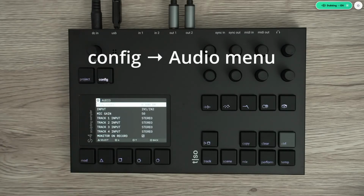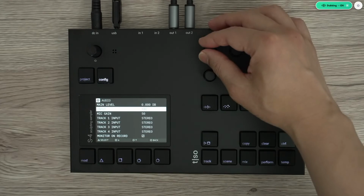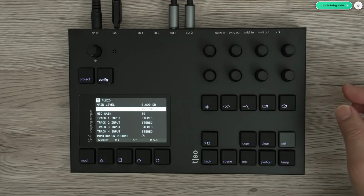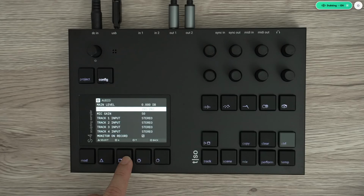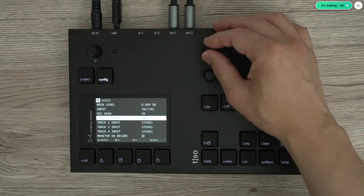The main level is the main volume. You can leave it at 0 dB. Inputs are IN1 and IN2, mono or stereo. There's a built-in mic on IN1 and a headset. For audio into the S4, use a mic preamp or mixer to set the level depending on your gear, like a mic, synth, or guitar before sending audio.